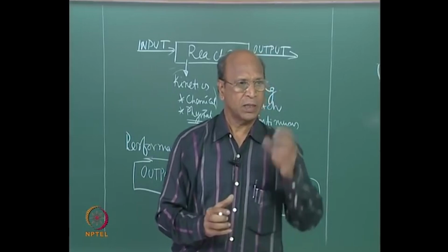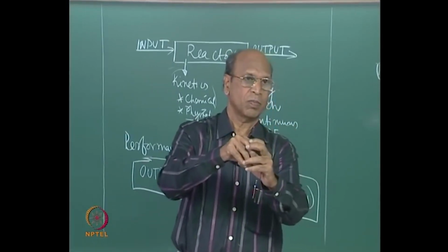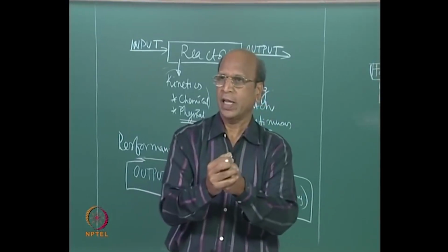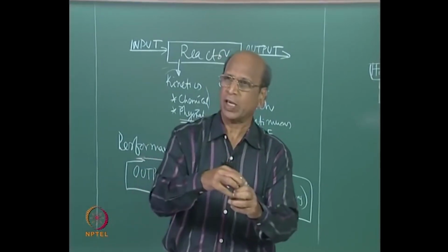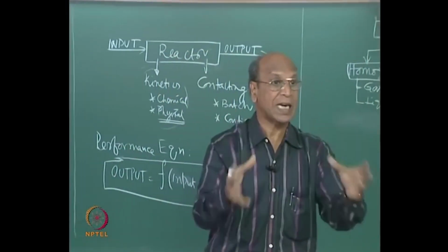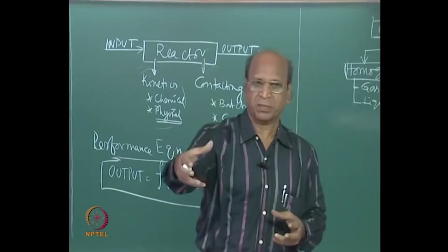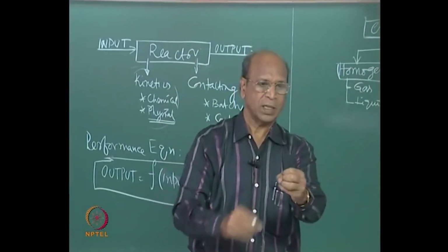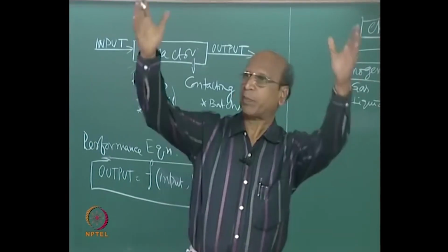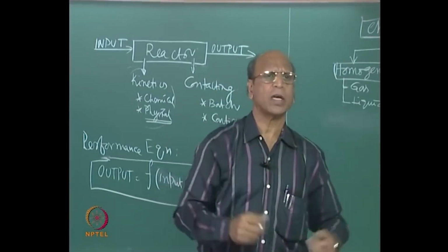Volume of the catalyst means this volume has, inside, again void volume. Are you talking about only pure solid volume, that means everything crushed together and then you will have no pores at all? Are you talking about that, or are we talking about the volume of the particle, or are you talking about the volume of the reactor? Correct, no? Reactor has now additional voidage. Packed bed, you have the particles, this particle is porous, some void volume there. Now all these particles are kept in a reactor, where between the particles there is some more void volume. Which volume are we talking about?